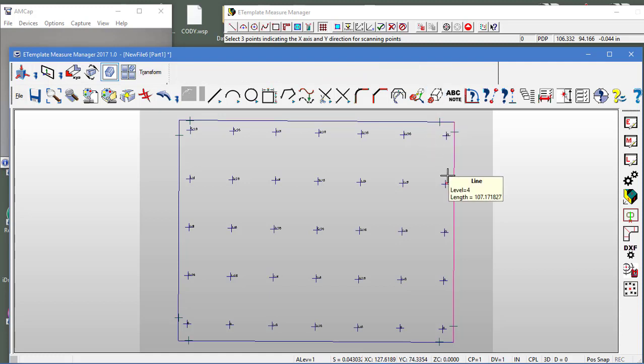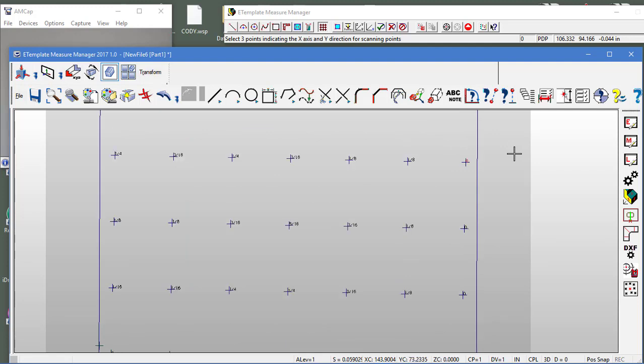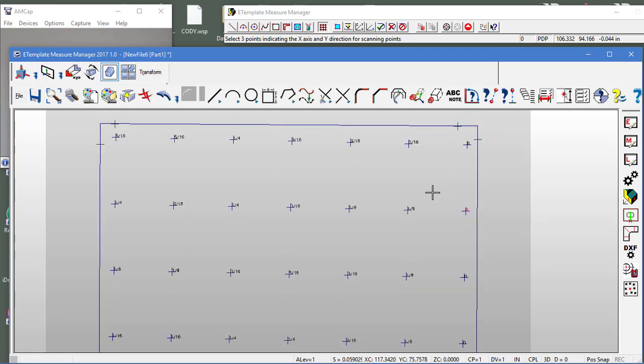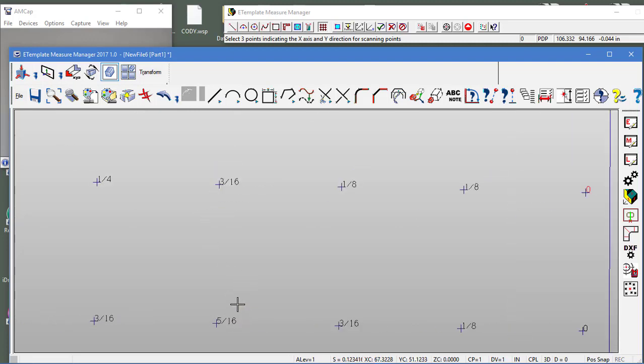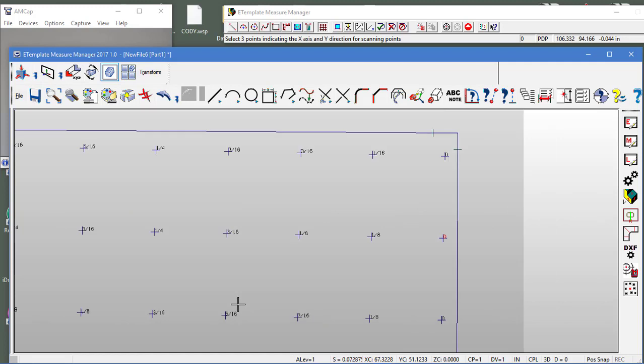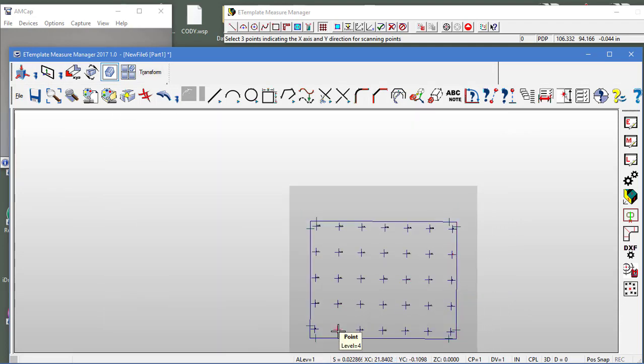The farthest out section of this wall is going to be a 0 in red. So here's our farthest out section of the wall, right here. And if we zoom in a little bit, you can see other parts of the wall are as much as 3/16, even 5/16 below, lower than that section of the wall. So all of these zeros are at the same level, but this is the one that perhaps is some 4 or 5 decimals out, the farthest out one.